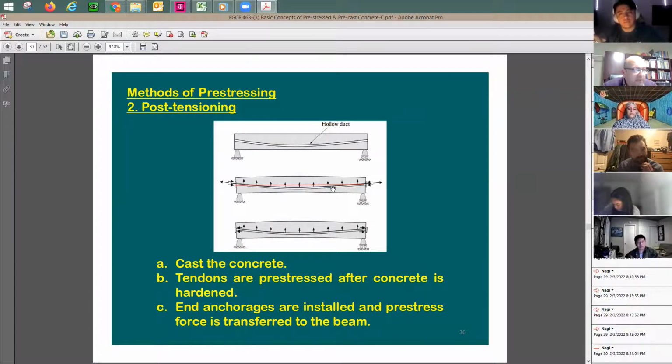Also, pushing the grout here is not an easy job, and it's done in certain projects, not any post-tension project. It's going to be in special projects. The good thing about the grout is that it's going to provide also some anchorage, like bond between the cable, the strand, and the concrete. So first between the cable and the sleeve, and again the sleeve and the concrete is in one piece. And you need also to know that the sleeve has a deformation, and the deformation here provides the anchorage between the concrete and the sleeve.